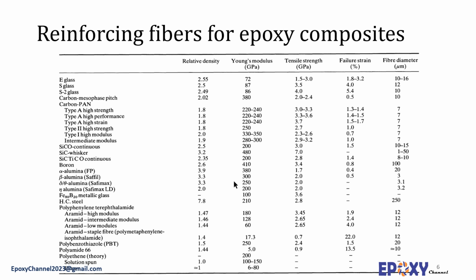Graphite or aramid reinforcements are dominating where light weight is crucial, for example in aerospace and sport goods applications. However, where economic considerations are more important, glass fibers are the reinforcement choice. Aramid fibers such as Kevlar, Nomex, and Teflon are the main polymeric fibers.